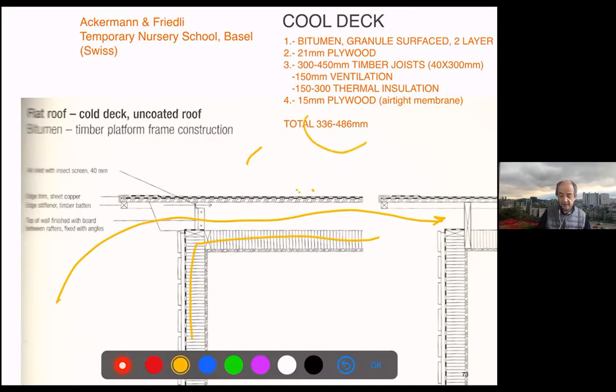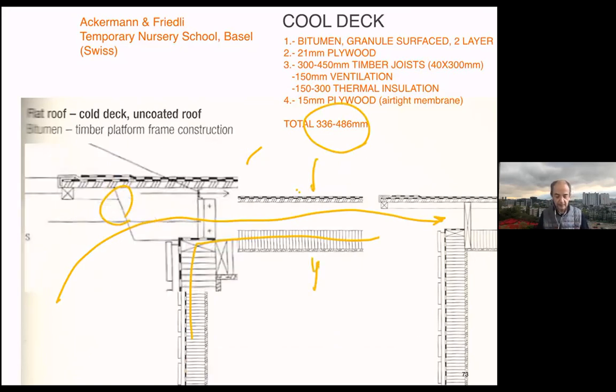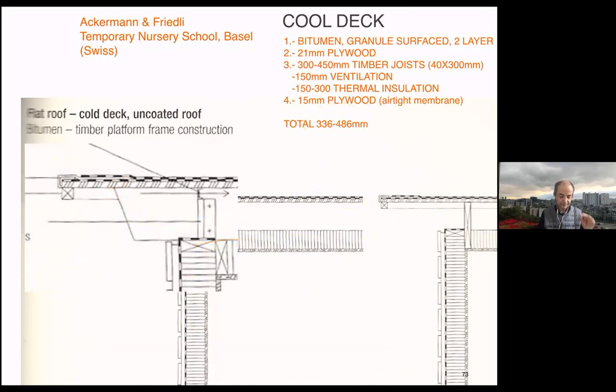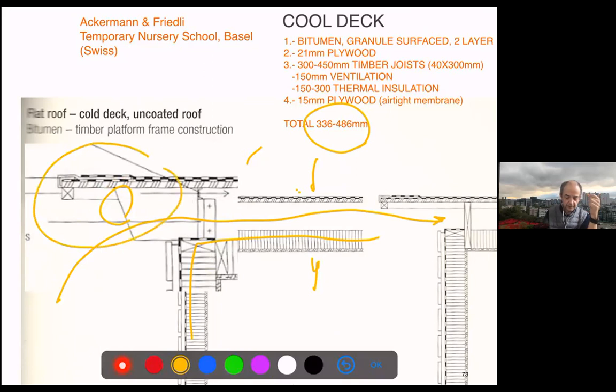But having this ventilated doesn't make the roof thinner, though we'll have to make it very thin at that end. And you see the pain of the work to have those endpoints with a metal protection, which will support the two layers of waterproofing, overlapping at some point, and one element which gives you the drip, in which the joints are always hidden.